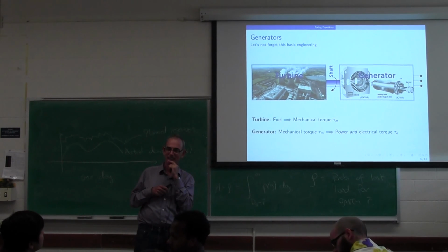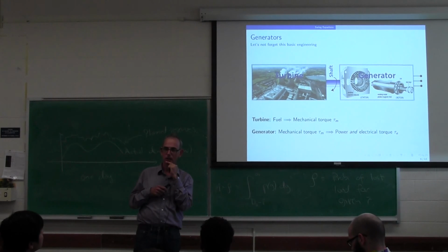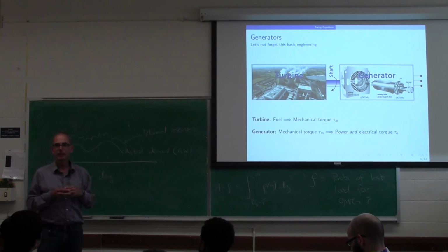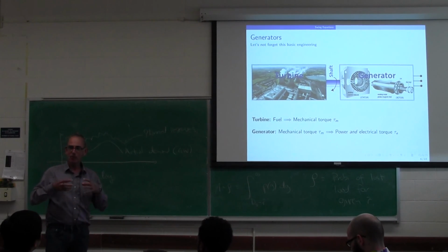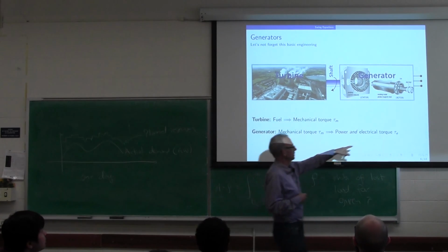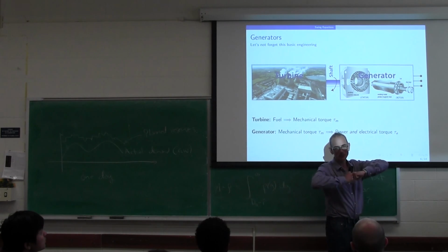You're going to talk about the inertia from these moving machines keeping the frequency stable. Yeah. And when you go so far off the map, it's only half a hertz. Once you get to that point, it's almost like the point of no return. You're going to get these frequency spasms. I'll show you some simulations next week to show this. You've got these generators coupled through electricity and torque, and it's almost like they're on the same shaft. So if they're at different frequencies, it's like the shaft will break. But that's a really coarse explanation.